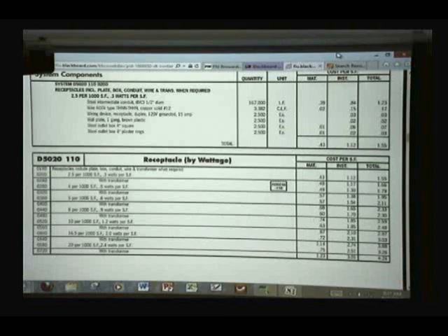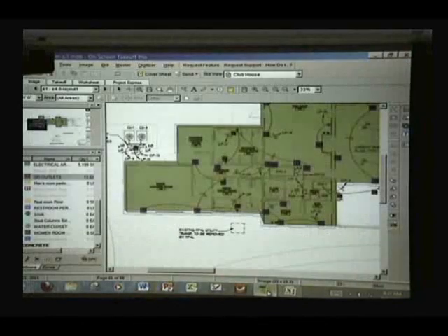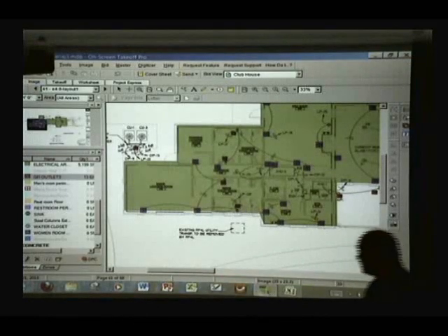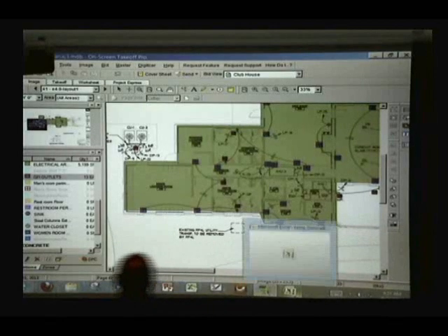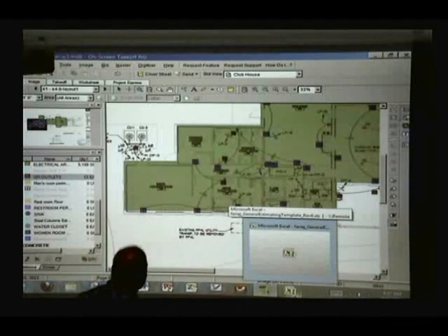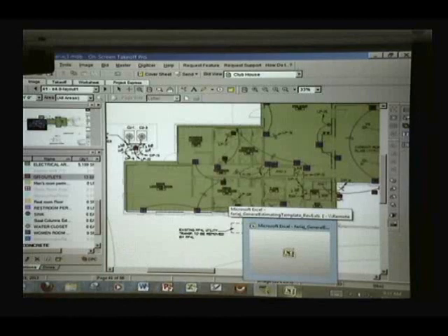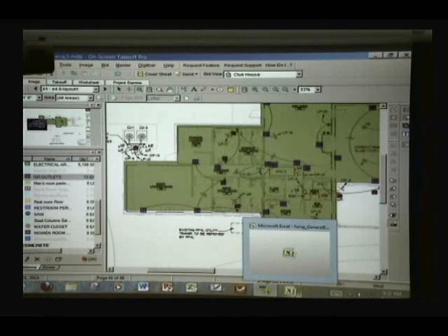All right. So what are we going to do now? Okay, so we're going to modify. I guess I could just add both of them. Well, let's do one calculation at a time. Now we're going to treat the GFIs and the duplex outlets as if they were the same, right? So how many do we have per square feet? We go back to 10, right?